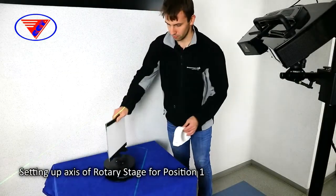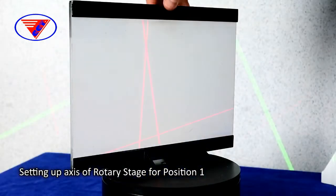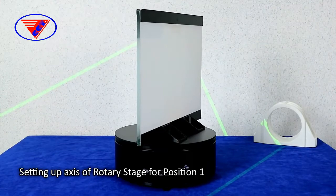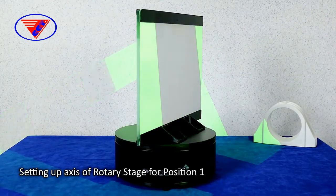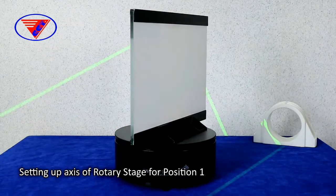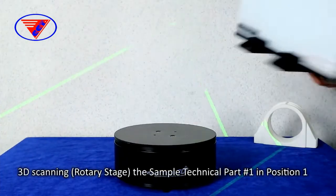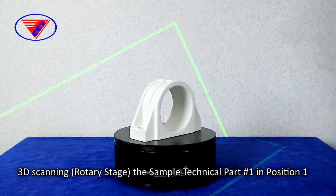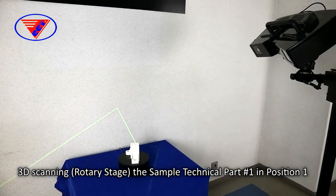If the position is set up, by using the calibration plate define the axis of the rotary stage. After the calibration, put the object on the rotary stage and start the scanning process. We will scan the object around with the step of 30 degrees.